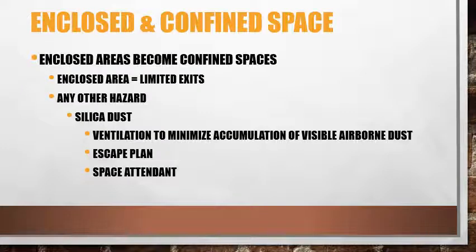Silica dust also is one of those hazards that can change an enclosed space into confined space. Enclosed areas become confined spaces when any other hazard is present. An enclosed space has limited exits. If you add another hazard to it, it becomes a confined space. Silica dust is one such hazard.